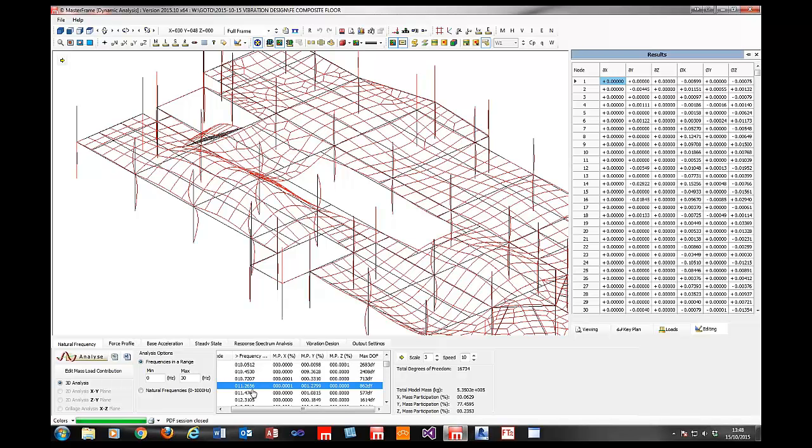And the P354 says to us, for instance, it tells us on page 12 that if the frequency of the floor is high compared to the forcing frequency, and it says for walking activities up to a maximum range of 2.5, this corresponds to greater than 10 Hertz. So that effectively talks about the fourth harmonic of 2.5 being 10 Hertz. In my case, the fourth harmonic is 8.8. So therefore, any fundamental frequencies above that really might be best to assess it using the transient analysis rather than the steady state.